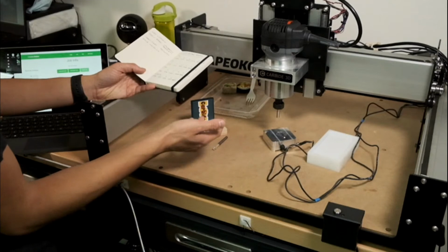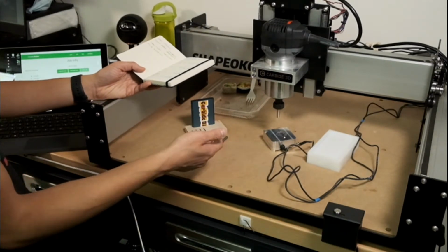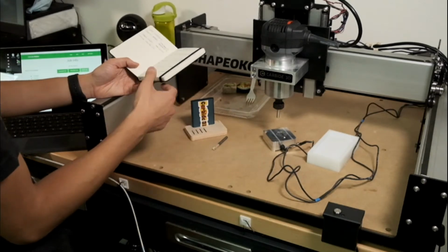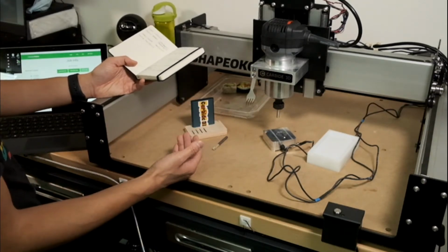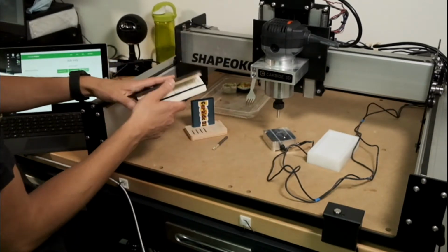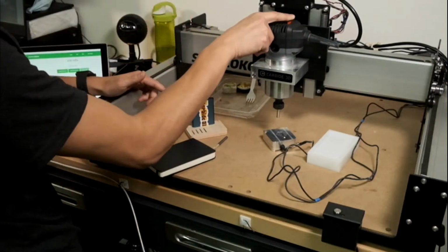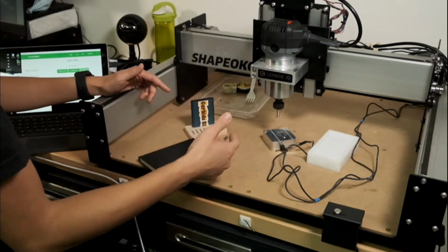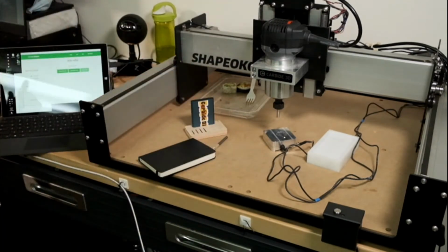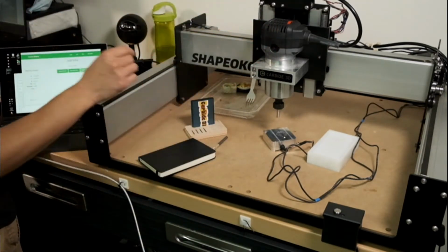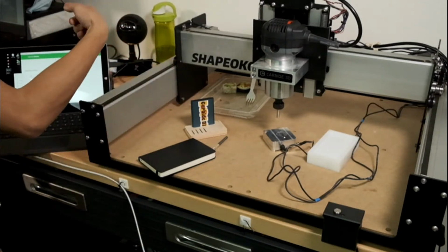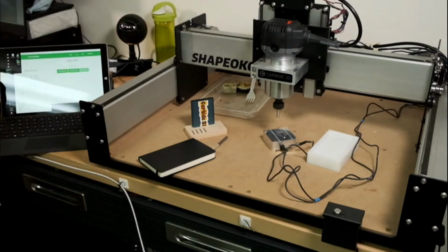It's really not a big deal. If you're cutting wood and you're off at like 5,000 RPM, it's still going to work just the same. In aluminum, you have a little less wiggle room, but still, within 3,000 is plenty. So it's like the number plus or minus a couple clicks. So you have a really large margin for error. So I wouldn't worry about the RPM and how accurate this is. It's really not going to kill your end mill. And as you saw, I crashed an end mill over on the Nomad. End mill's fine.